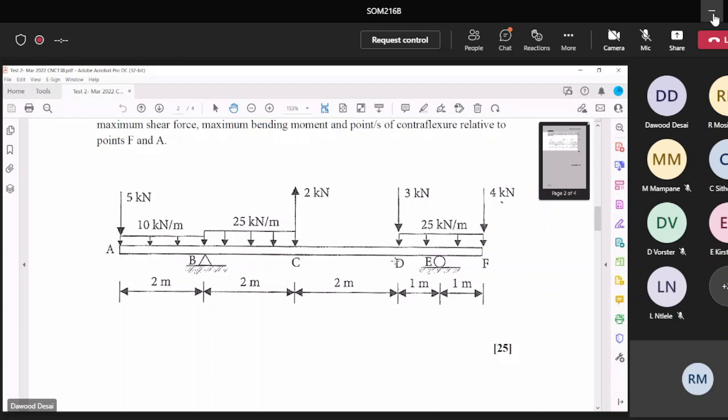You can write down the answers, but I think most of you guys got this right, which is encouraging. 60.4 is RE. Okay, they call it V here because it is, of course, a shear force. But you can write RE. And then the next one is RB, 69.6. And very important, the check. See, some students are still not doing the check. They're very brave, they have 100% confidence that their two reactions are right.